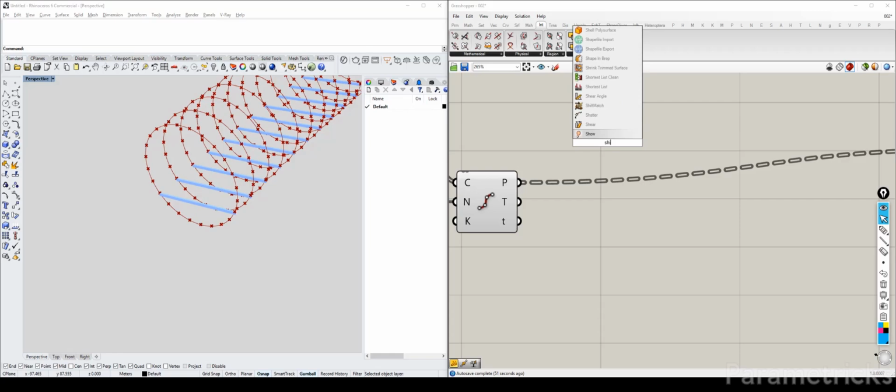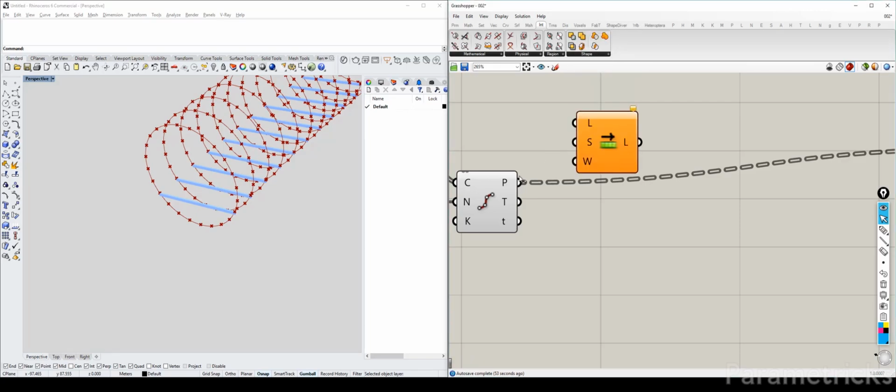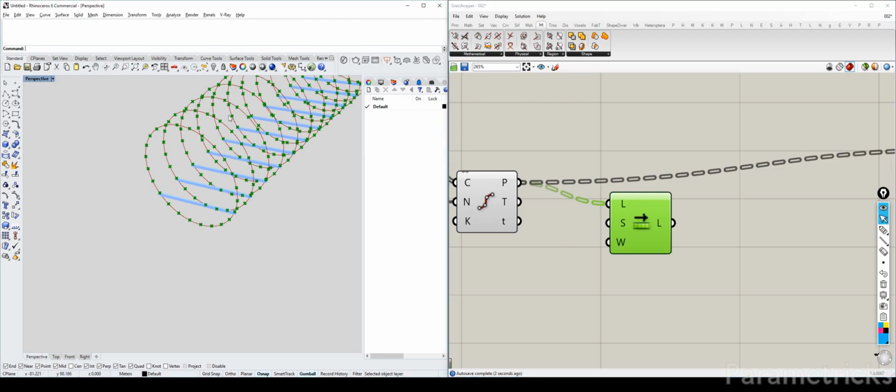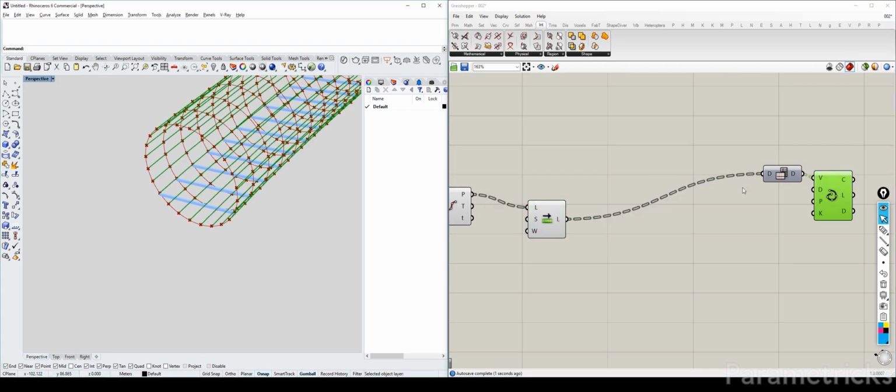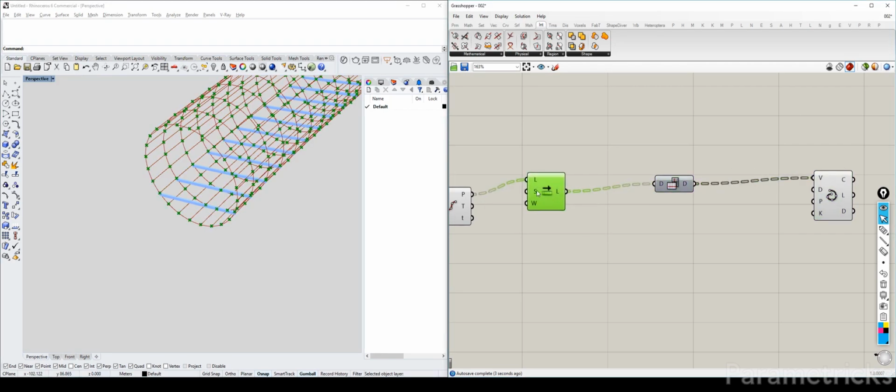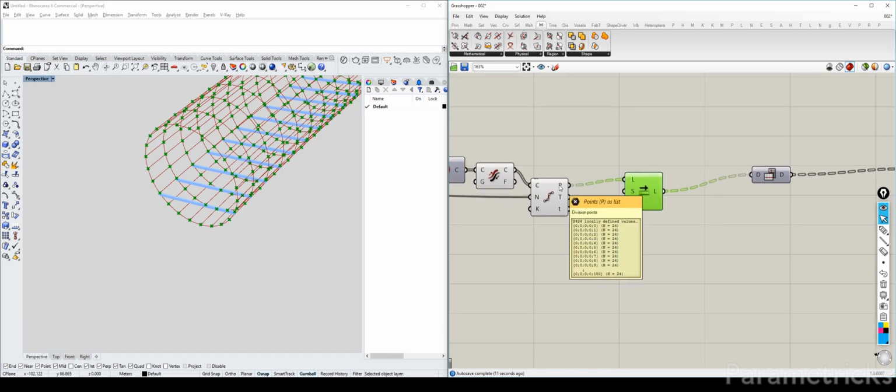One thing we can do is we can just say shift list and make sure wrapping is on so that it keeps on shifting it and does not end. And what you get now is it shifted all the points by 1, which doesn't help us. What we want is we want to shift each of these, let me simplify this so I can see it easier. Each of these trees, these 101 trees, 1 by 1.